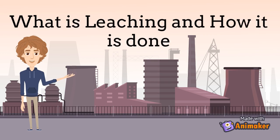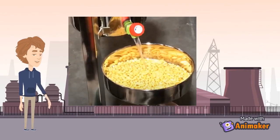Leaching is the separation of solutes from solids using liquid solvents. It is done by bringing the solids in contact with a liquid solvent, so that the solvent could extract the solutes out of the solids. For example, the separation of soya milk from soya bean. Can you recognize this as a leaching process? Here, soya milk is the solute extracted from the solid phase, soya bean, by contacting the soya bean with the liquid solvent, water.